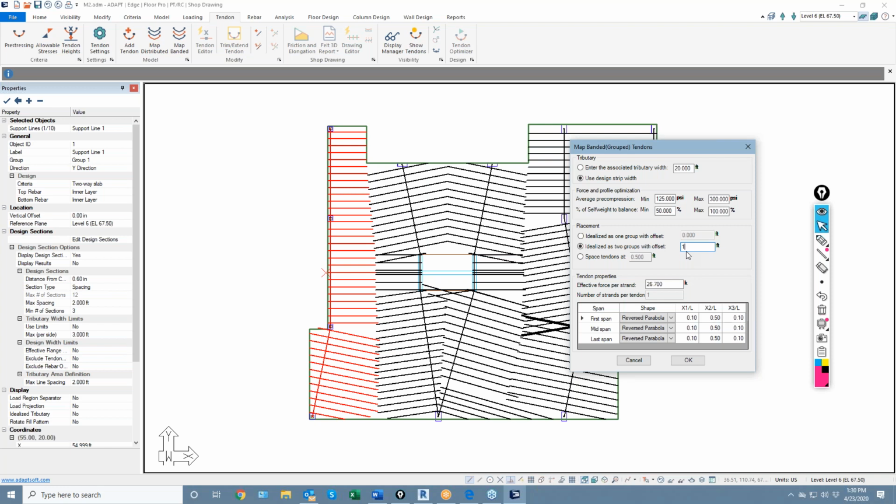So when the tendon is modeled, it actually gets chunked out into sections or segments, and the solution gets dependent on the discretization of the segment and also the refinement or lack of refinement of the shells. So you could have shells every 10 feet.